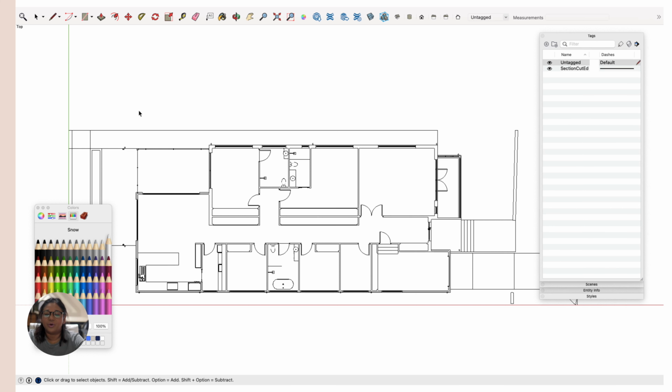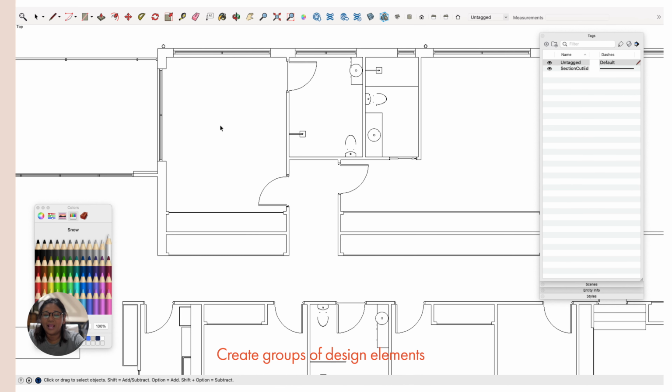We're going to have to create tags and tag all our sections here that we would like to have as planes and lines. Here we have a room that has a doorway, and we want to actually create the floor, but we want to have that doorway on a different tag so that we would later on be able to take that doorway away.